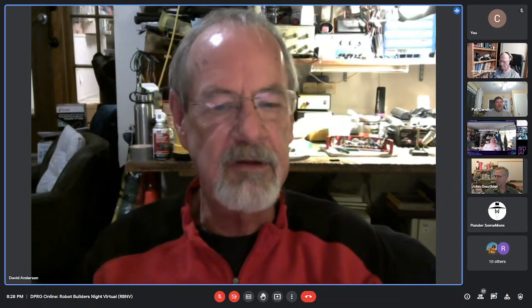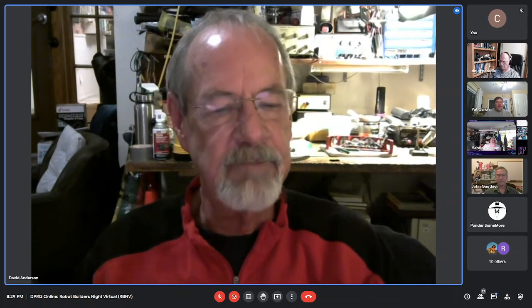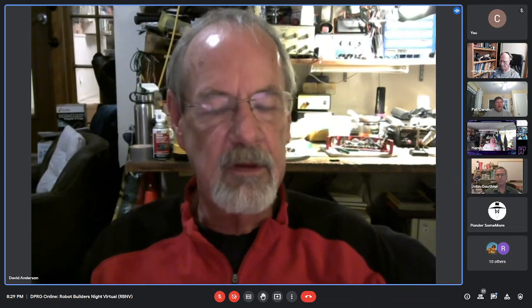Obviously, well, I shouldn't say obviously. What I've found is that once you add a rate gyro or an IMU, it totally changes what you're doing, because the wheel odometry itself depends on contact with the floor. So with an IMU or a gyroscope, you can actually pick the robot up real quickly, rotate it 90 degrees and put it back down, and it'll turn back around and go where it was headed. It knows which way it's going. And I noticed that when I tried to correct it. Yeah, it can be annoying.